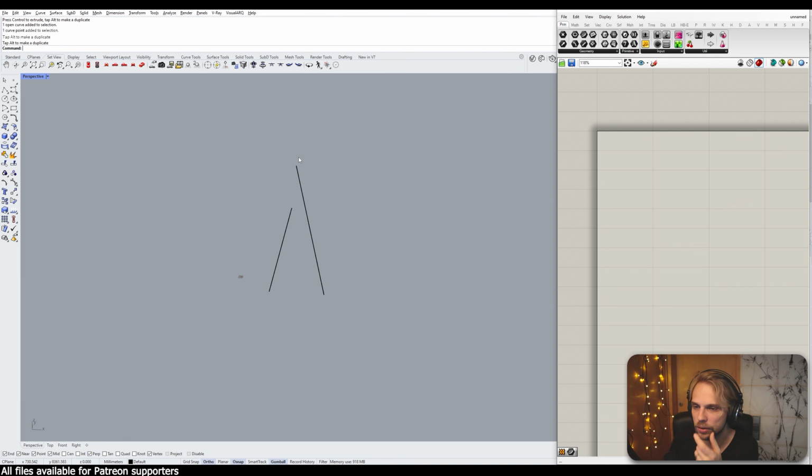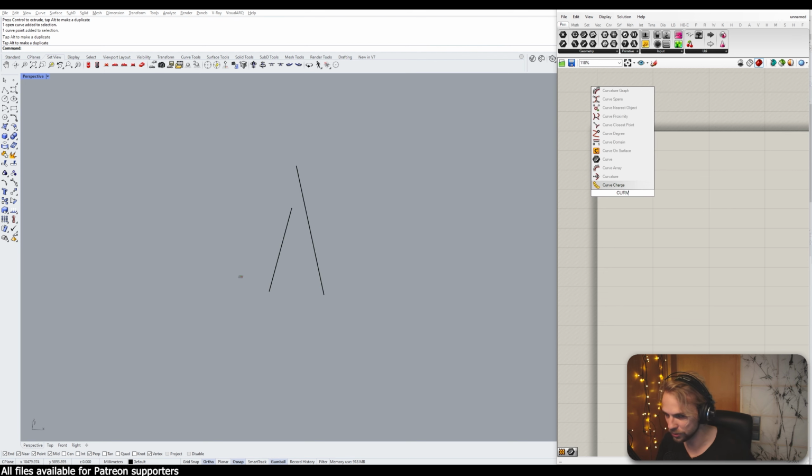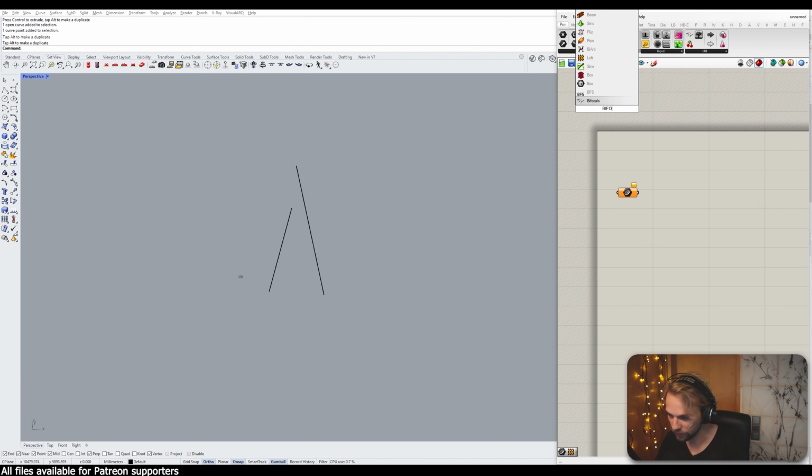I will want a Grasshopper definition. So if you don't have Grasshopper opened, open it up now. I will want my Grasshopper definition to automatically place my beams along these curves. How do I do that? Well, I first need to reference in the curve component. Don't worry about this.